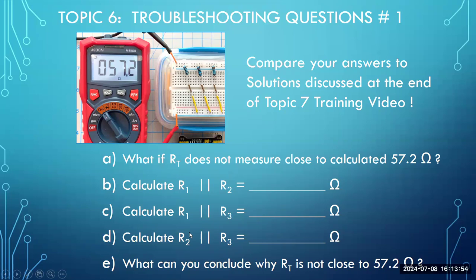What this is suggesting is perhaps one of the resistors is defective, one of the resistors could have been burnt out, or one of the resistors is not connected properly. If one of the resistors is not connected properly, very likely you're going to measure some number that you've calculated here, okay? So let's go ahead and try some of these calculations.